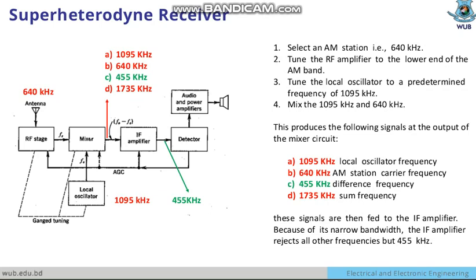In previous lectures, I have told you about some oscillators and some amplifier sections. The tuning section is known as the tank circuit, so that has to be tuned, as well as to have good coordination between the AM band and the receiving frequency.